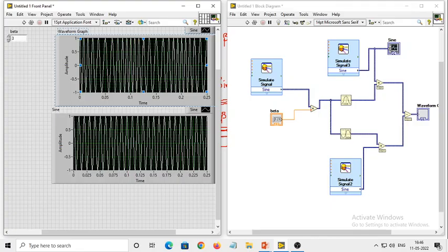Now you can see there is an increase and decrease of frequencies, which is the basic principle of FM signal, where you will be having Fmax and Fmin, and this increase and decrease of frequencies is with respect to the message signal. Whenever the message amplitude is high, you will be having Fmax. Whenever the message amplitude is less, you will be having Fmin. Such variation in frequency is observed in an FM signal, and you can clearly see such variation in the graph.